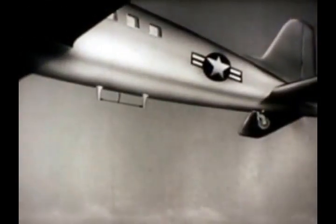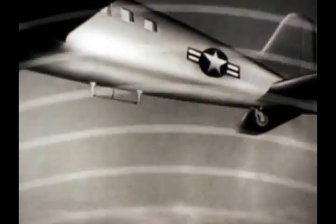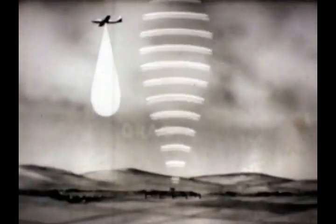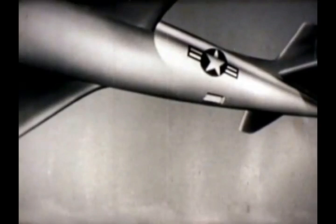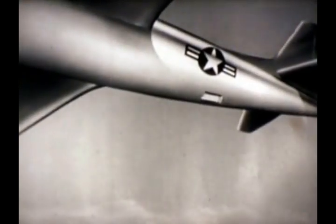Many aircraft have a marker beacon receiver. It has a specialized antenna system designed to receive a particular pattern in a particular manner from a ground station. The marker beacon antenna is mounted on the underside of the aircraft and may consist of a half-wavelength wire. Every antenna system has a reception pattern similar to the pattern which it can transmit. Such an antenna system receives ground-transmitted energy within a wave pattern shaped like a teardrop. But this wire antenna causes drag. Therefore, on high-speed aircraft, the antenna system is recessed.